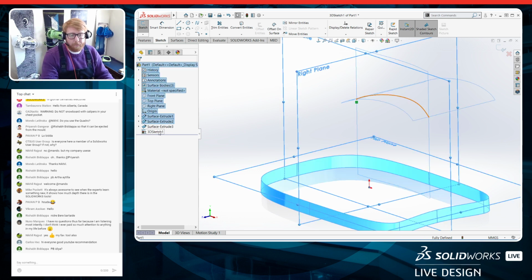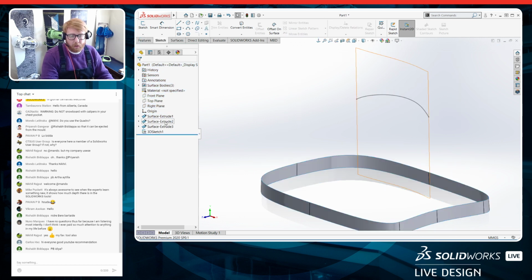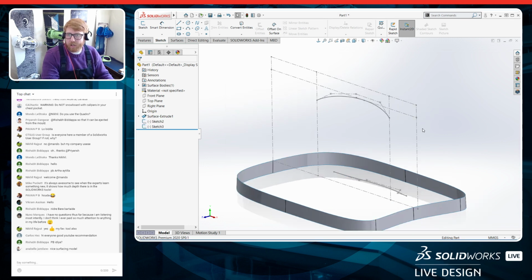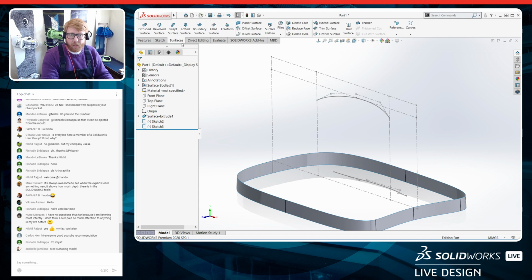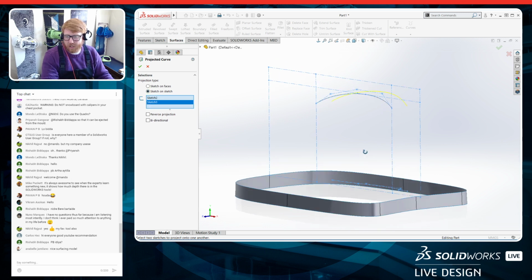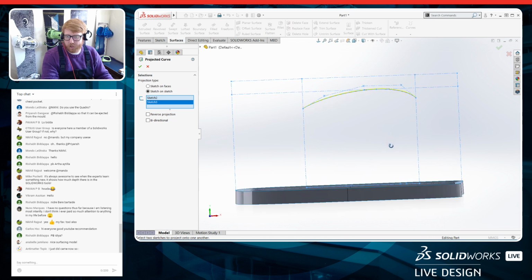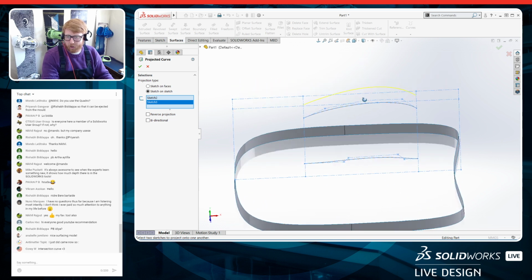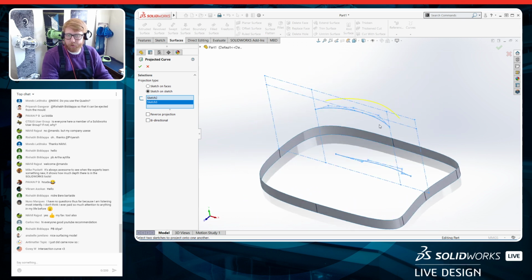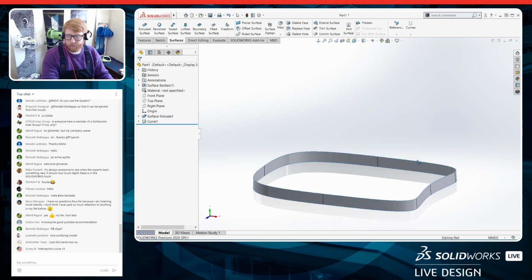But there's this other tool where you don't even need to use the intersection curve of the 3D sketch. Inside of the surfacing toolbar is curves, right? Maybe you've come up here for split line. You can also go into project curve. And if I go to sketch on sketch, it's essentially going to give me the exact same curve. It's as if I projected that sketch in this direction and also in this direction. It's where they would meet up, right? So that's a project curve. Cool.